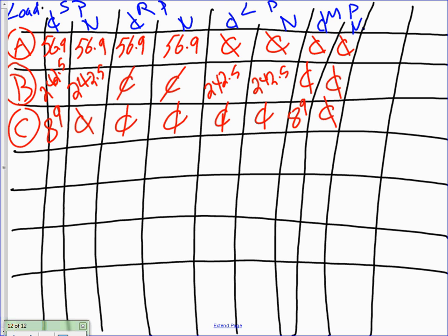Okay, what comes after C? A, B, C, D. What was D? Motors. And the total demand for the motors was? 770. Now, just a quick reminder of the motors: we have two motors, 20 horsepower three phase, and two motors, 10 horsepower three phase. Did you hear me say anything about single phase? So what do you think the neutral here is going to be? Big fat 0, not just 0. All these motors are going to be fed from a mechanical panel.